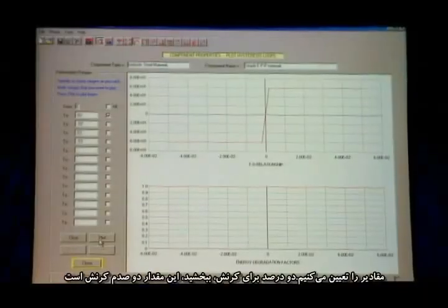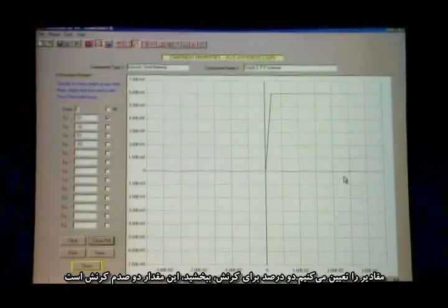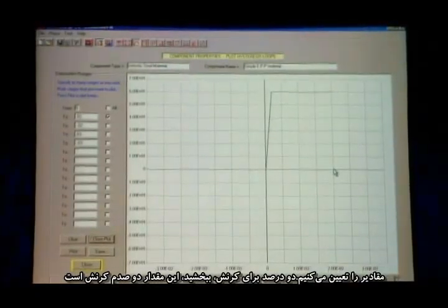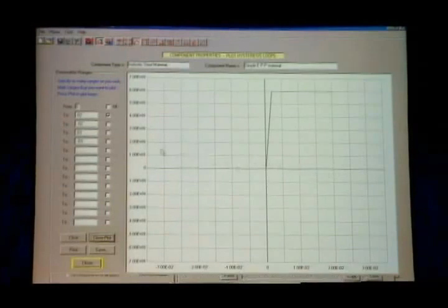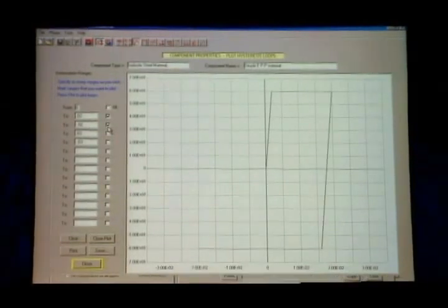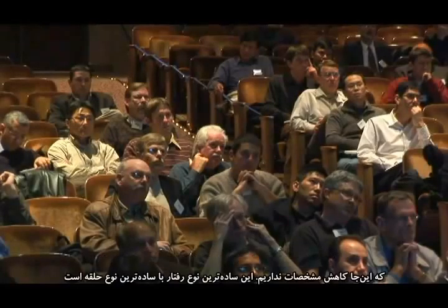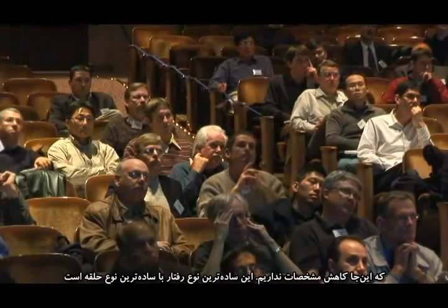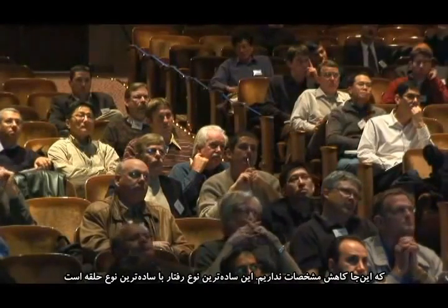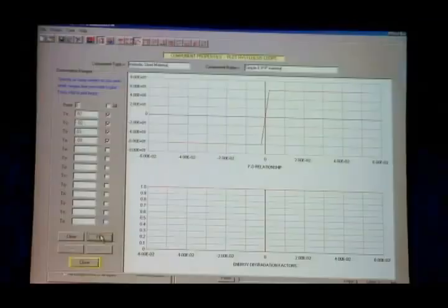So I've said, let's go out to 0.02 rotation. 0.02 strain actually. This is not artificial material, don't worry. Then load it back to minus 2% and up to plus 3%, then minus 0.3%. There's no degradation here. This is the simplest type of behavior with the simplest type of loop. This is the one option that you would have.